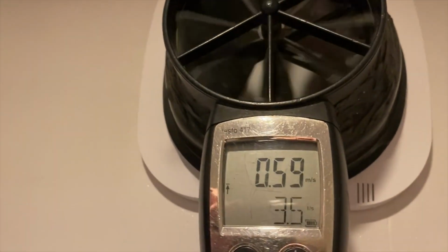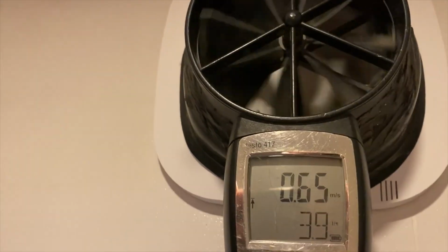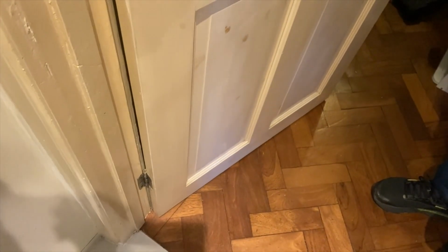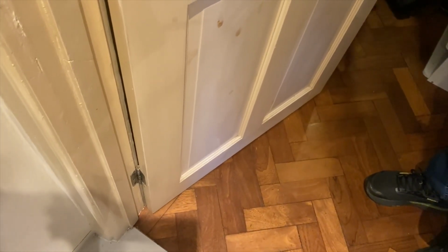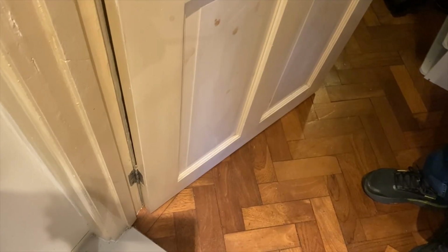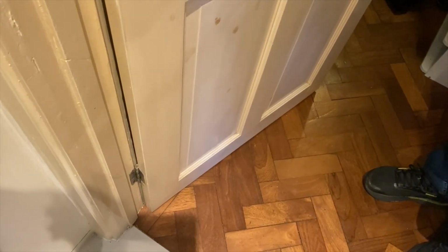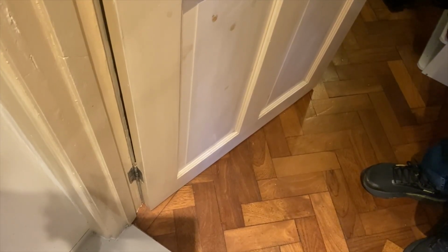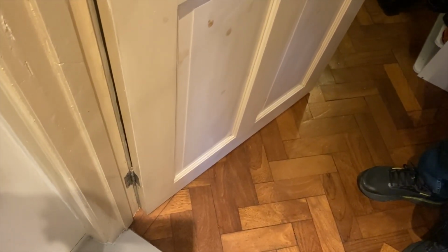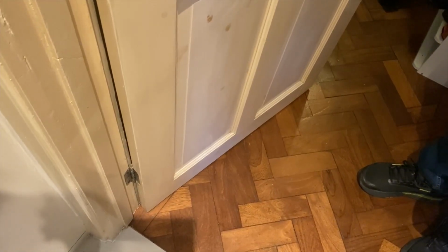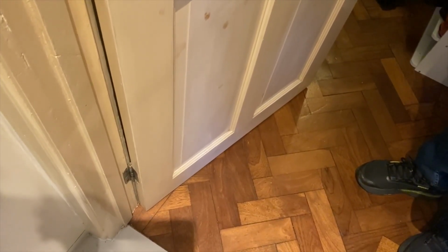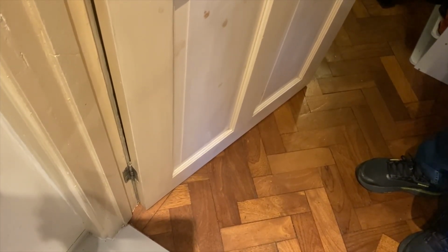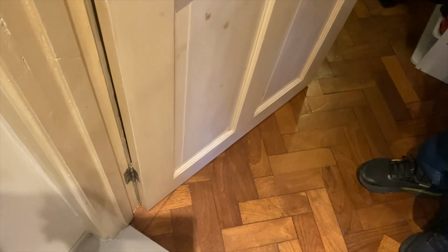So very little air is coming out of this one as well. We'll turn it off and have a look, see what's happening here. So far, there are three things that have come out really. You've got high relative humidity, a high dew point. Internally you want to keep the dew point below the outside temperature, and it's relatively high at the moment. So that's number one. Number two, that's caused by excess vapour being generated in the property. I can see immediately two issues that need to be addressed.